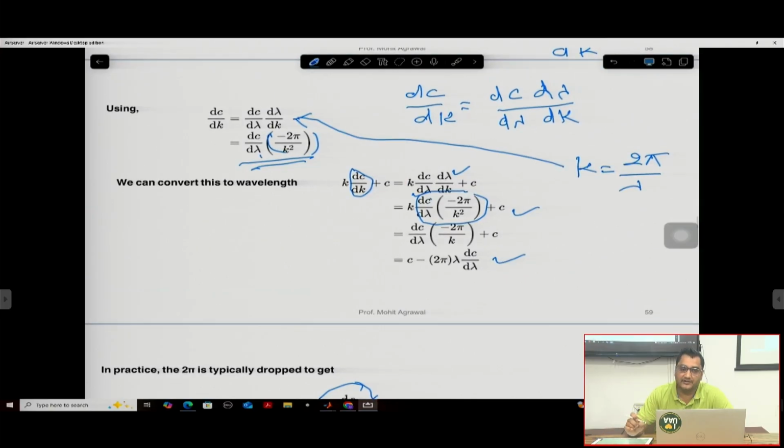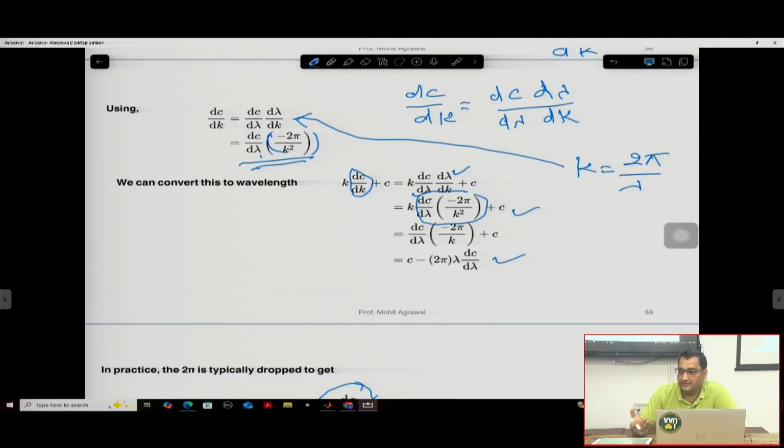You might have studied the array of geophones in the MASW technique, where you keep a geode connected to several geophones in a channel, and then you place it in an array in the field. Thereafter, using an active source or a passive source, you generate some source energy, and that is recorded at several geophones in the array. Then you do some processing, and thereafter you come up with the dispersion.